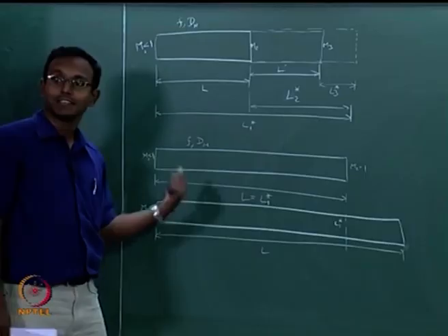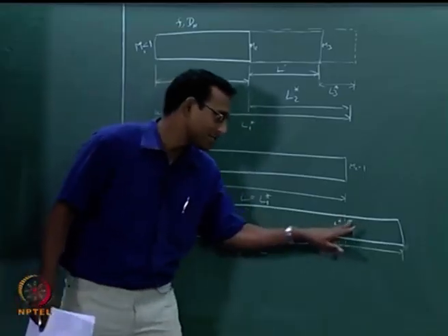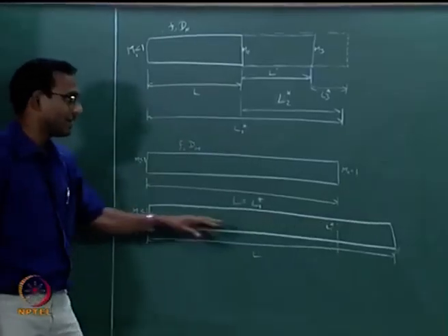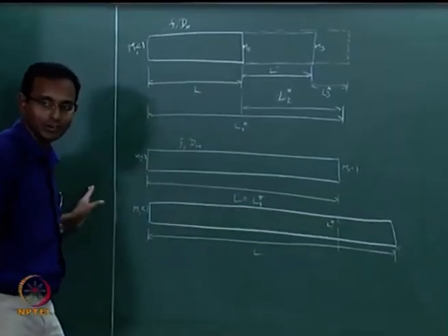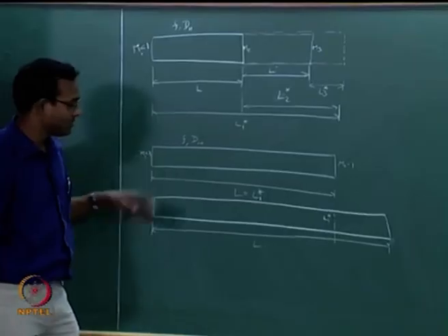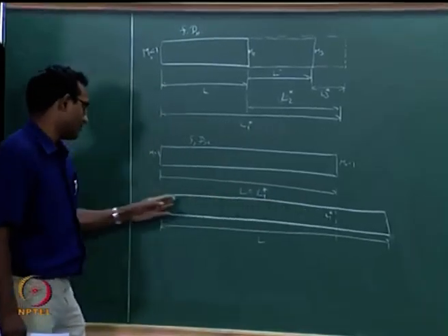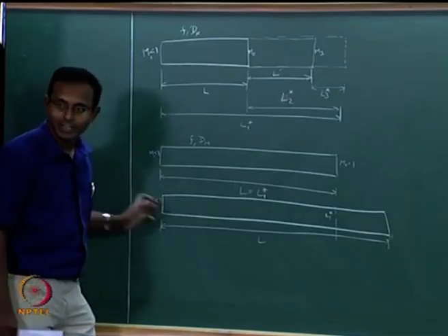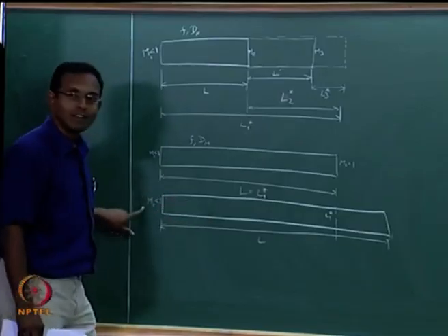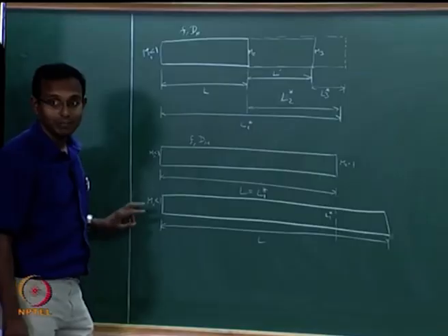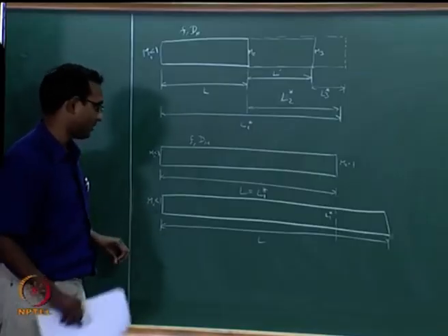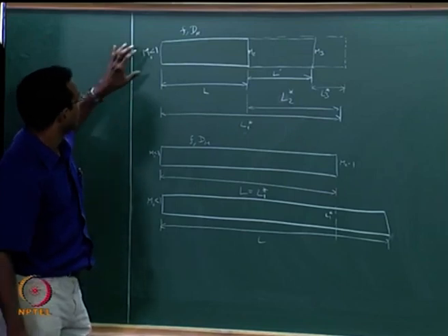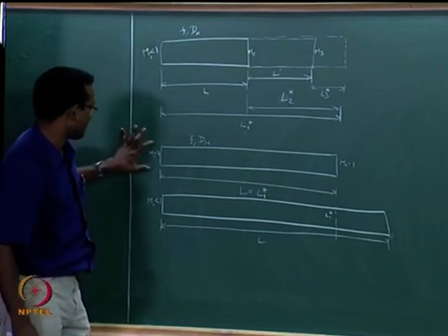It will decrease, it will send out extra compression waves from this excess length, such that those compression waves go, and it is subsonic, so it will go faster, it will reach this point. We are thinking only steady state as of now. So all those compression waves will make this flow come in slower. So M1 will now change to M1 prime, which will be less than the M1 value, such that it is equivalent to thinking about, let us say I will pick this problem.